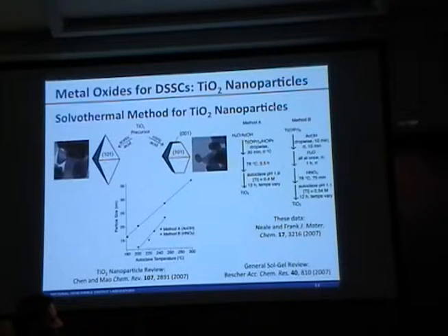And basically I found that if you control all the conditions perfectly, and you don't deviate, and everything's the same except for your temperature, so this is your autoclave temperature, you have a sol, which is basically an incompletely condensed titania precursor, and then you heat it up in an autoclave, which is simply something that seals up, and you can heat water to 200-300 degrees.